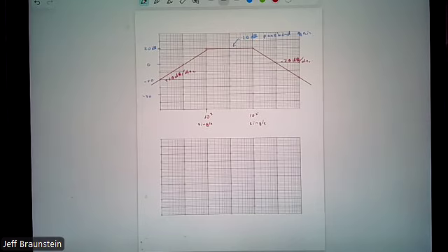Right. Not quite. Well, there's two things. Our starting phase is not right. But remember, when you cross the pole, how does the phase change? Across a pole, phase changes by negative 90. And also, when you go to high frequencies, when you get away from that change, phase becomes constant.